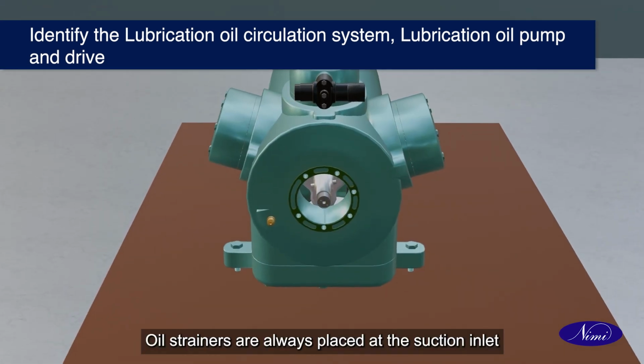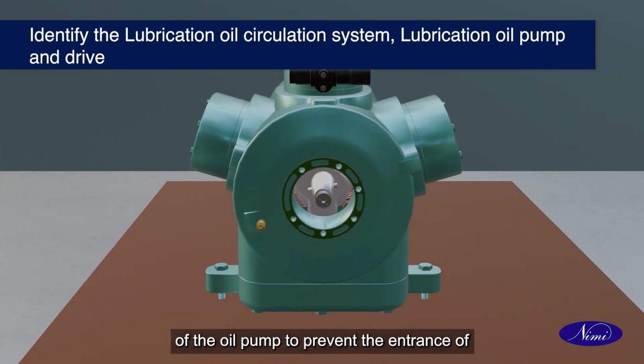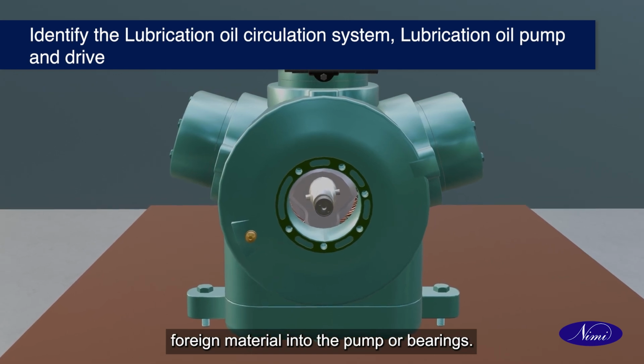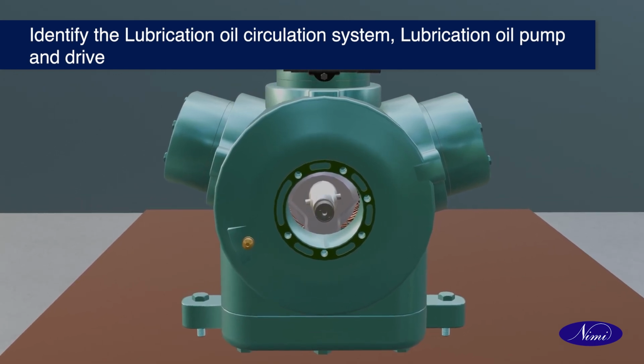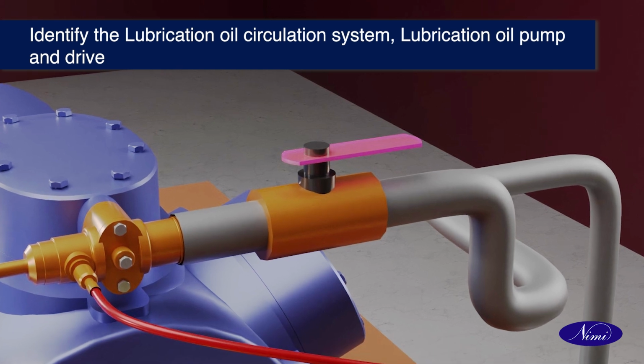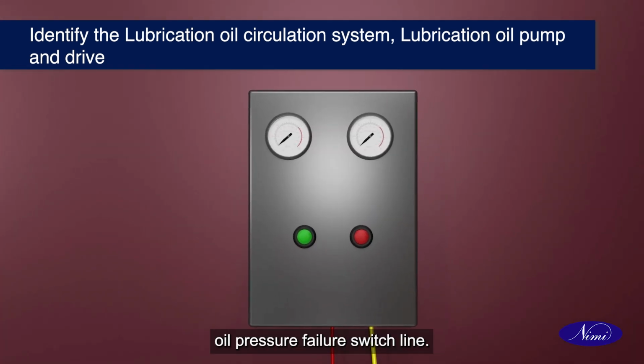Oil strainers are always placed at the suction inlet of the oil pump to prevent the entrance of foreign material into the pump or bearings. Identify oil pressure regulating valve. Identify oil pressure gauge and oil pressure failure switch line.